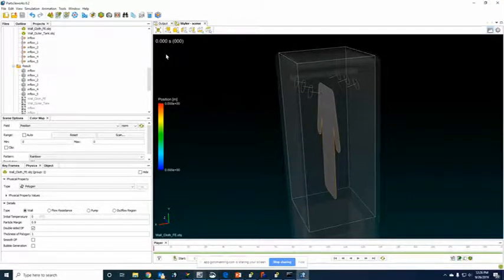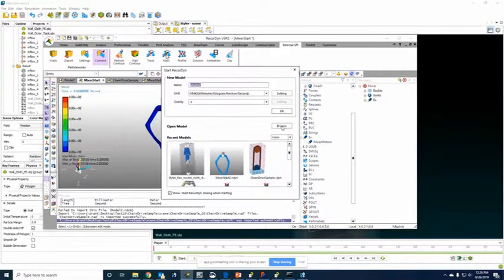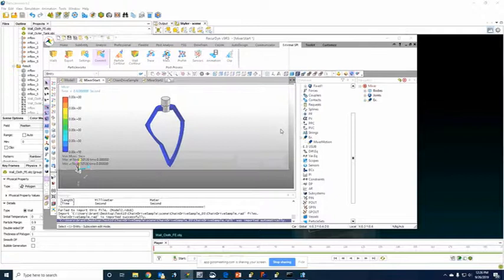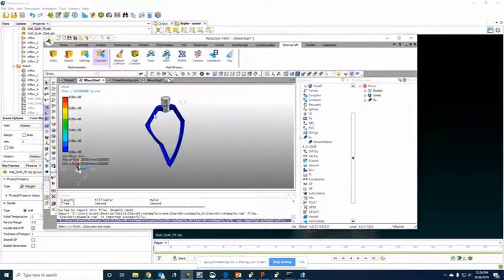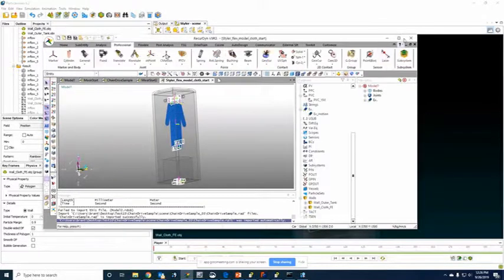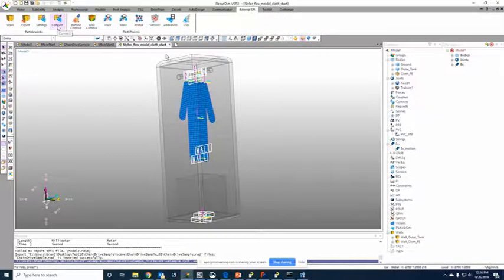And so now from this point, all you'd do is you'd browse to where you saved that in the scene folder. You browse to your file that you created. And now in the external SPI file, you make sure that the connect is highlighted there. So if you turn the connect off, then it will run the simulation without connecting to Particleworks.